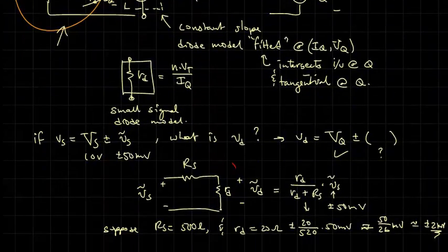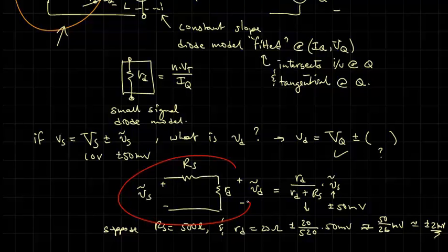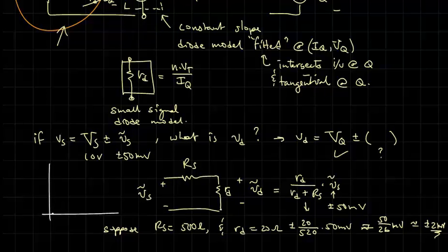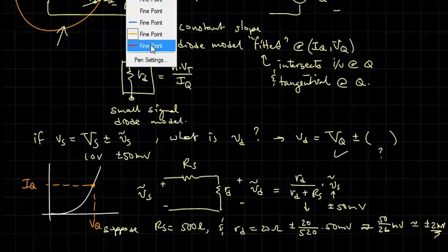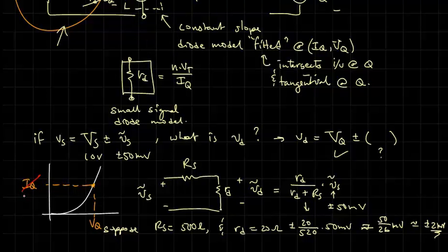Furthermore, when we use just the small signal, here I can redraw this. We've got our diode curve, and let's say we're operating right here at an operating point. So this would be IQ and VQ. It's like we use another set of coordinates.